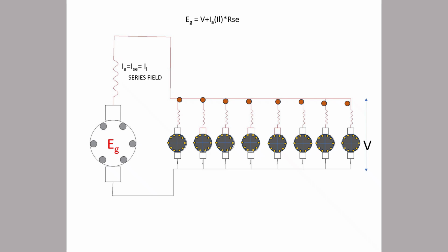Here the voltage induced in the inductive coil is due to the change of current or voltage in the AC wave to pulsating DC. So it will reduce that pulse and we will get smooth DC. And when this DC passes through the DC series motor, the motor will rotate and the locomotive will run.